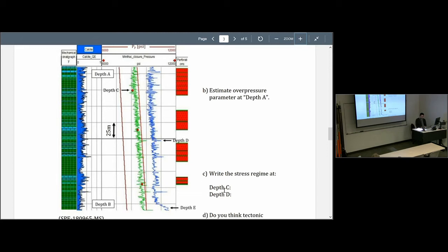So at depth C, which is this one right here, at that particular depth we see that the lowest stress is SH min, intermediate is SV, maximum is SH max, and that would be strike slip, right? However, look, at depth D, where we have this spike in stress, probably caused by a very stiff layer at that location.